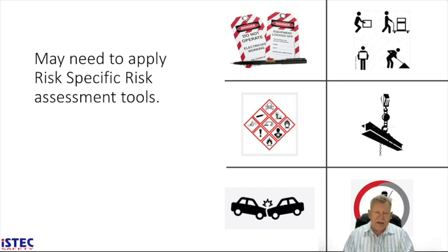Working at height requires a fall prevention plan, where I need to look at where we are working, what the external hazards are, what the surfaces are that we work on, and what the potential is for me to attach somewhere. What can I do to prevent the fall, how can I arrest the fall should a fall still happen, and then also, how do I rescue a person once he has been arrested during his fall? So that is a specific tool that we use for working at height.